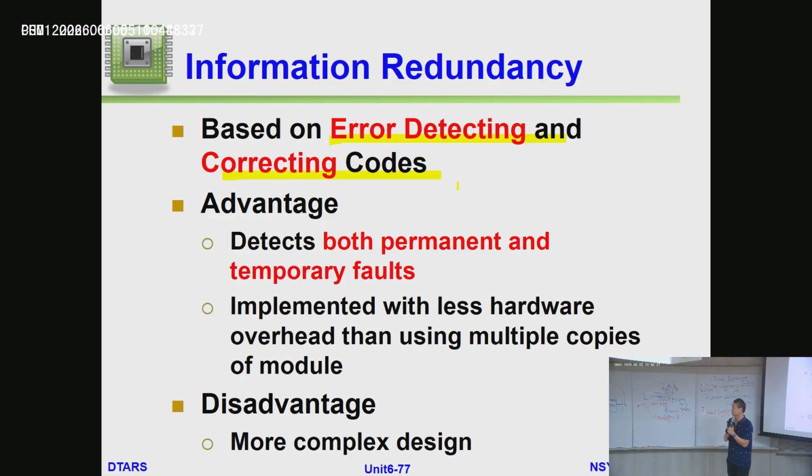So you can put your attention on encode and decode. For encode, we add more bits into your signals, and then during the decode process, we use those additional bits to check if there are any errors in your data, and also do the correction.